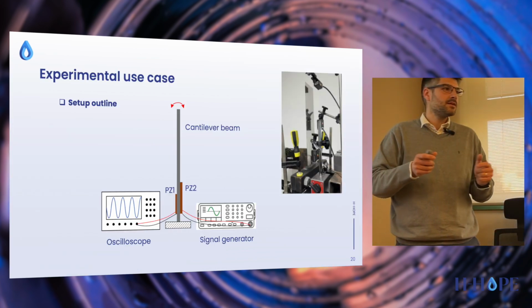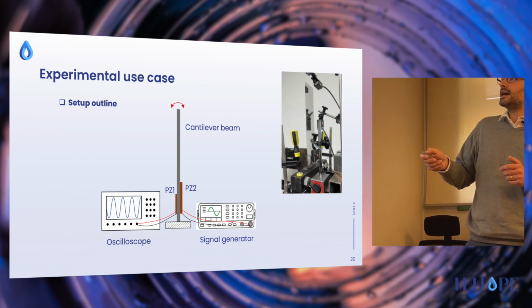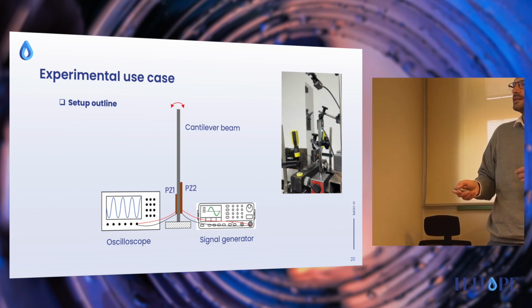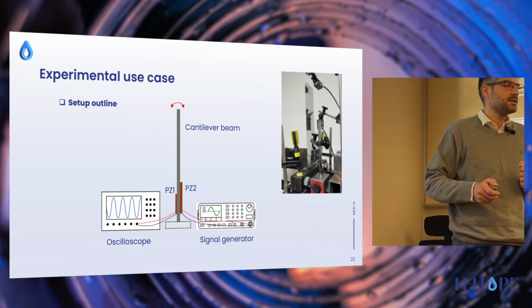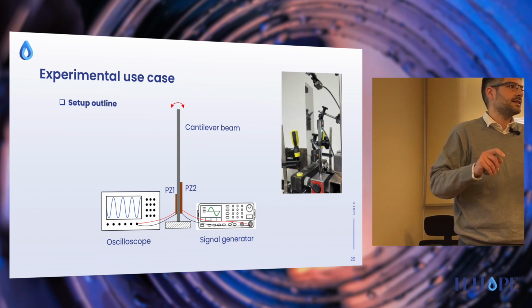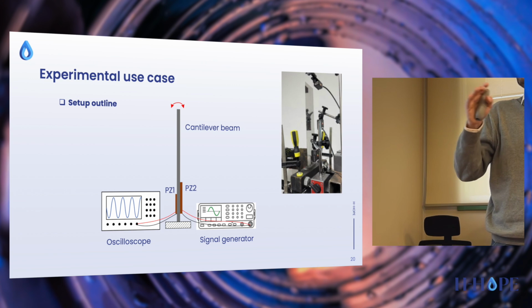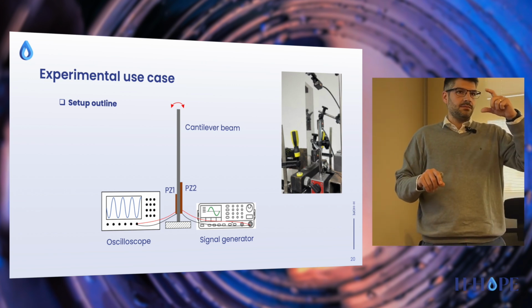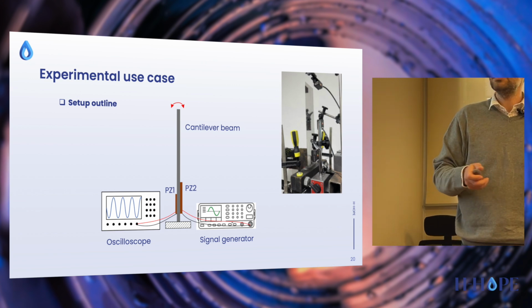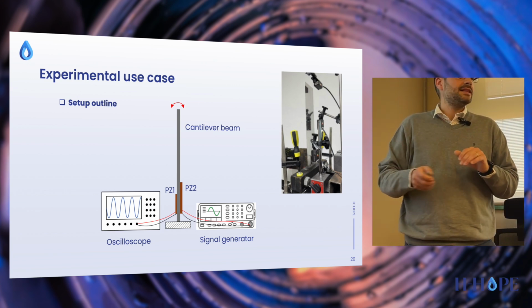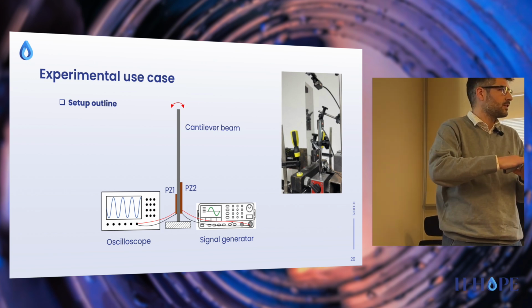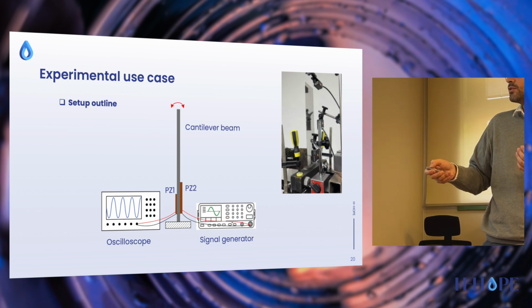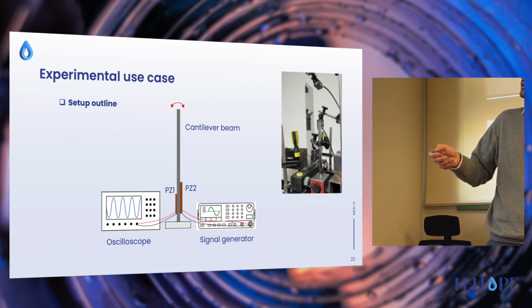experimental behavior. In this figure, we can see our simple beam that is fixed on only one side, and we have glued a piezoelectric patch on both sides. On one side, we have glued the bigger piezoelectric patch, that covers around 60 millimeters by 40 millimeters, more or less, and its polarization direction is transverse to the plane of the patch. On the other side, there is a small piezoelectric patch, and the polarization direction is in the same direction as the beam.